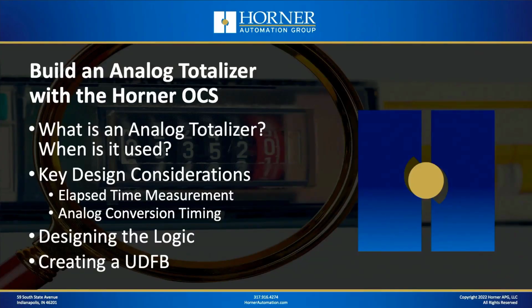Okay, so let's dive into our topic on analog totalizers, and here's how we're breaking down today's topic. We'll start with reviewing what is an analog totalizer and when is it used. There are some key design considerations. In order to do it well, you're going to have to measure elapsed time accurately as well as have accurate analog readings. We're going to talk about how we may need to design the logic to do analog totalizing in the OCS. And I've already created a user-defined function block that I'll show you at the end, that if you want to use for a future analog totalizer application, you'll be able just to plug it right in.